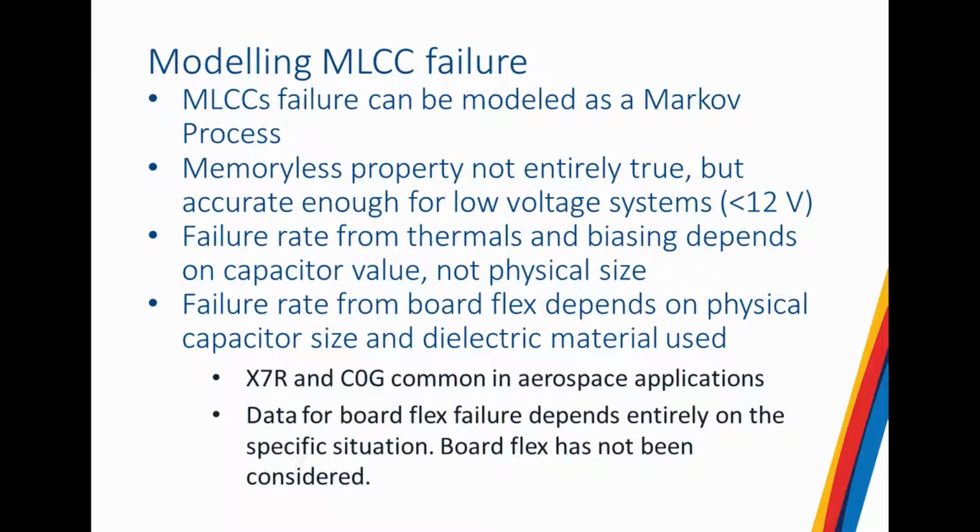The probability doesn't change. Now, as we discovered, this isn't entirely true for capacitors because they actually do depend on a few things like bias voltage. And so if one fails, the bias voltage of the other will actually change, therefore changing the probability in the Markov process.